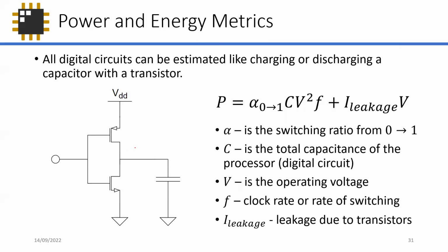Every time you process data, let's say in an adder or an ALU, you spend energy to process that data. You don't care how fast you do it, because usually fast circuits is proportional to power, so the speed, F, as you can see over here. But energy is not dependent on speed. It's rather dependent on how much computing you do. But we'll get to that next time.